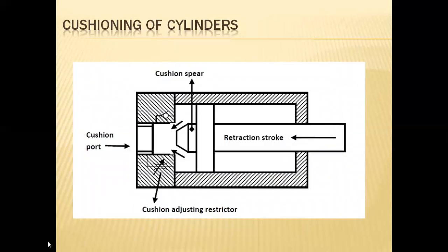When the stroke is retracted or a load is being applied, the fluid which has interconnectivity will enter, and this check valve opposes the fluid, and there is no doubt that the fluid will enter this particular channel, which maintains the constant pressure for this cushioning port. And here the throttle valve adjusts to the maximum pressure that can be withstood.